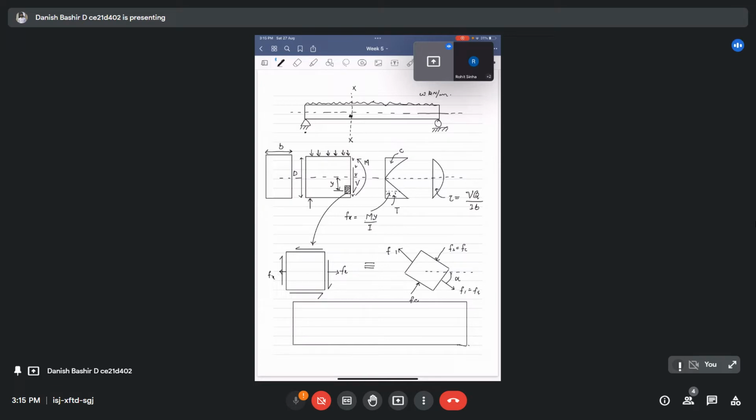When I see these principal stress trajectories, for example, I took this block here. If I took another block like here, another one like this here, in my beam section, I will get stress trajectories which will be having principal stresses only, not any shear stresses.